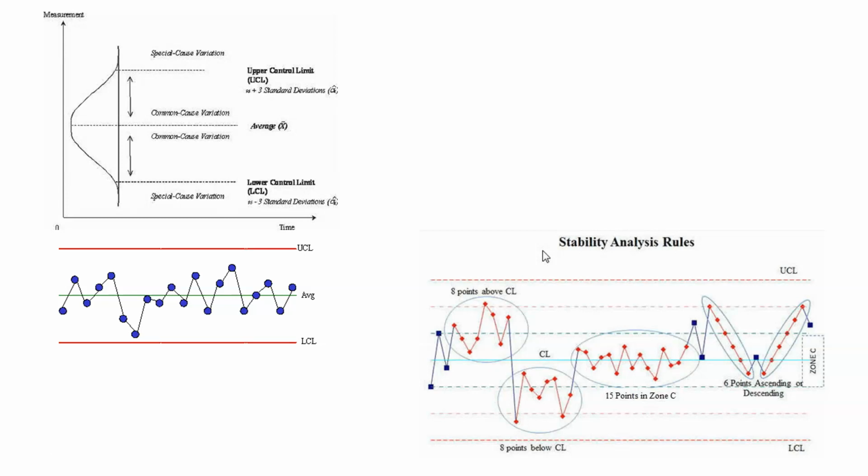And as you can see, a lot of these things that are also considered out of control conditions, which still land within the control limits of the chart, just don't have the randomness that you would normally expect of accumulated data. So we can look at these and determine them as special causes instead of common causes. They're labeled, we don't want to necessarily go through them in this video, but they do have names for each one of these sorts of activities in a chart.